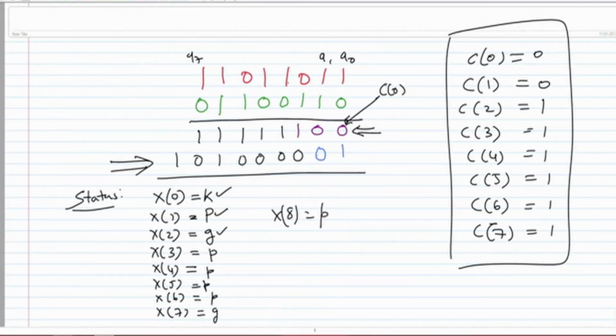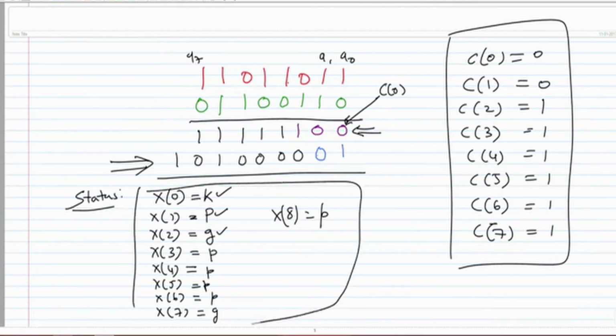Okay. So then what I do, right, is this clear? So what is the time required to basically generate these x values? It's constant time, right? We just use one AND and one OR gate for each. Kill I call as 0 0, generate I call as 1 1 and propagate as 0 1. Then basically I need one AND and one OR gate to generate these 2 bits. So in unit time I am able to find these x values, right? Okay.